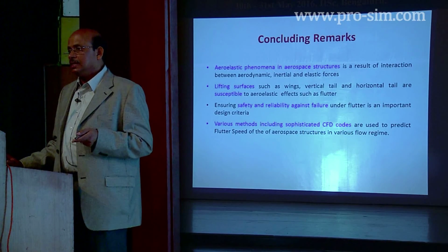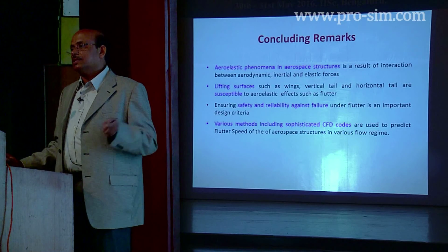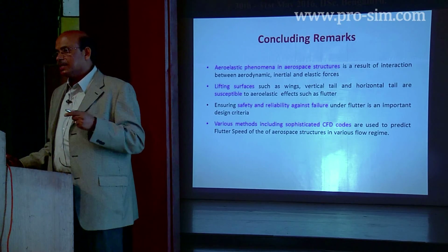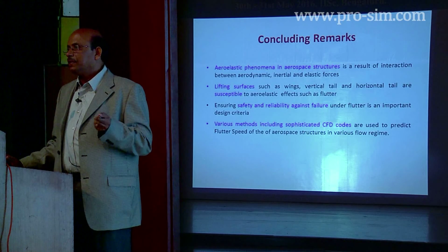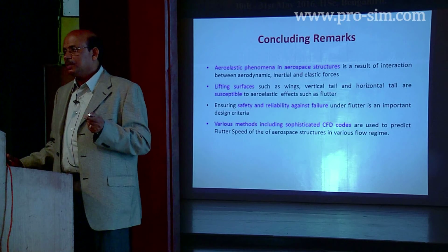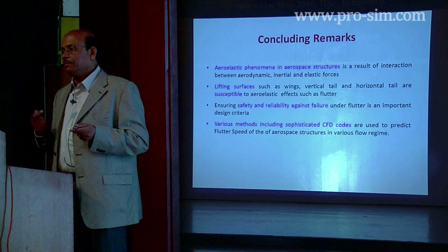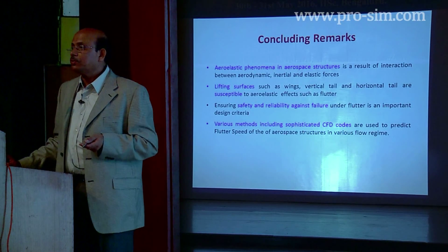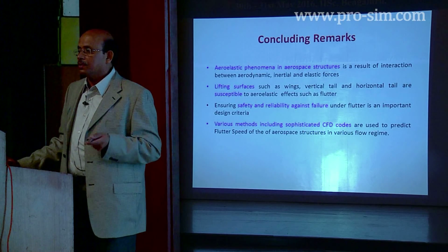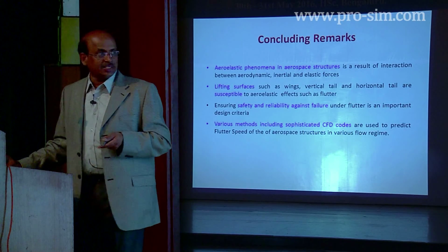In fact, the whirl flutter was done based upon classical calculations. We didn't use any FEM there. It was a typical 2-degree-of-freedom system, which we solved using MATLAB equations, and we gave the solutions. So various techniques we looked at that we are using for qualifying our aerospace structures.